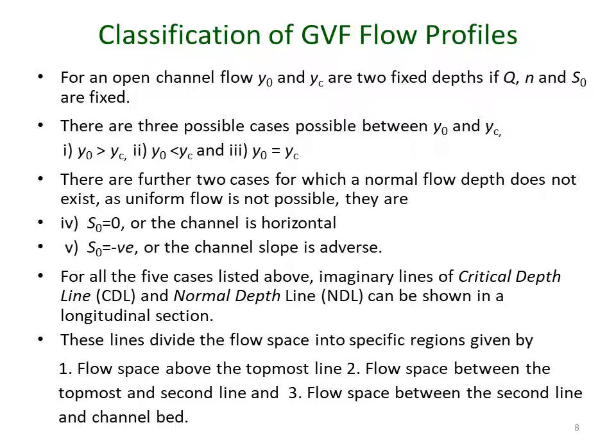And those cases are case number 4, where the channel bottom slope is 0 or the channel is horizontal, so S0 equals 0, and case number 5, where the channel slope is adverse or S0 is negative. So these are broadly the 5 cases possible for